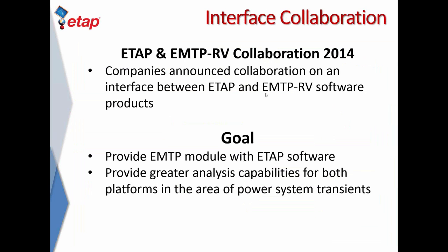So we have essentially collaborated with EMTP-RV in 2014, and both companies have announced an interface between ETAP and EMTP-RV software, which will allow you to perform EMTP studies as a module inside ETAP. The basic goal is to provide a platform that gives you greater analysis capabilities, especially when you're dealing with power system transients in the electromechanical domain and in the electromagnetic domain, using one network model and without duplicating the data entry effort.